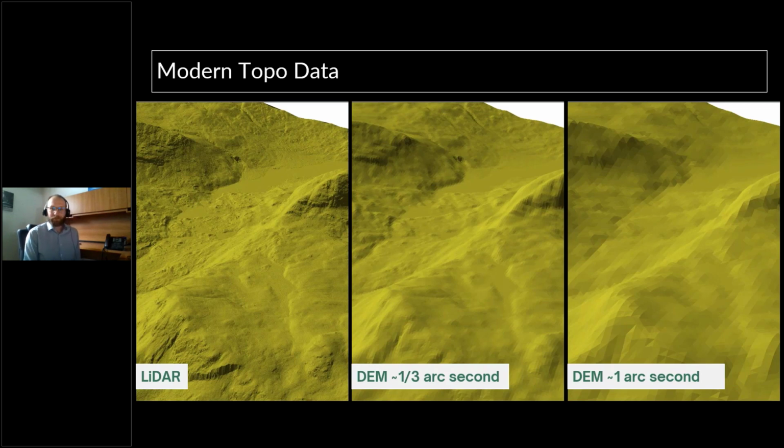Now, to the best of my knowledge, maybe with an exception of parts of Antarctica, anywhere in the world there is DEM data available. So at the most coarse level, there's the SRTM DEM, and I forget what that acronym actually stands for, but it's global coverage or near global coverage. The Arctic has a different coverage, but it's 1 arcsecond data, so about a 30-meter grid. It's free. So that's showing up on the image to our right now.